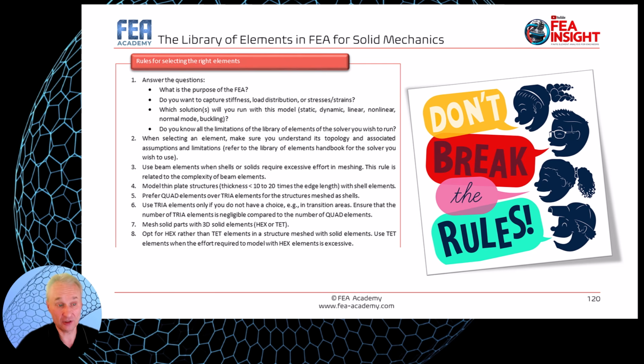Opt for the hexes rather than the tets, okay, when you use solids. And use tet elements when the effort required to model with hex elements is excessive. But in that case, you have to opt for tet 10 and never the tet 4.